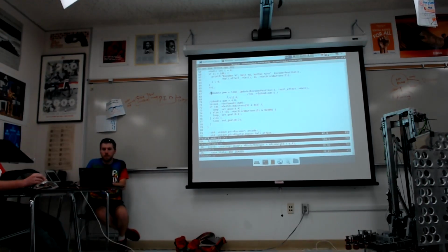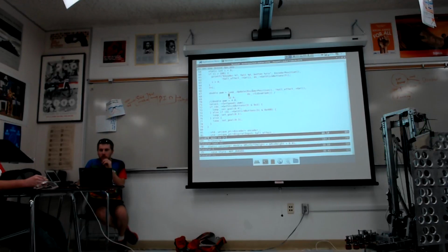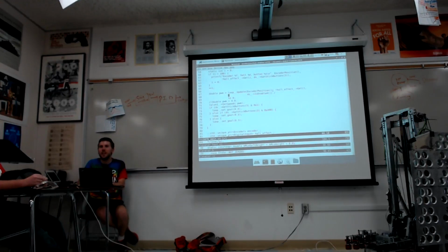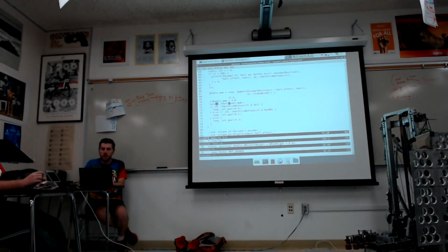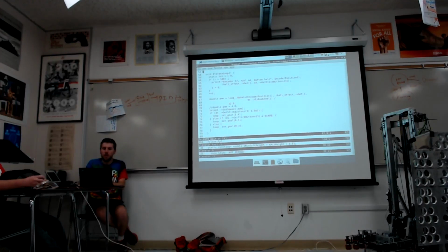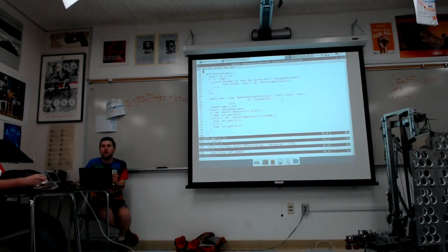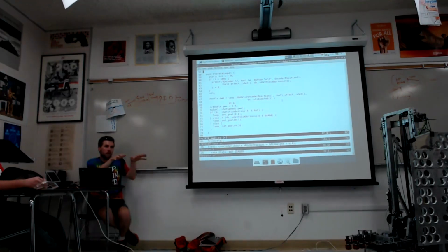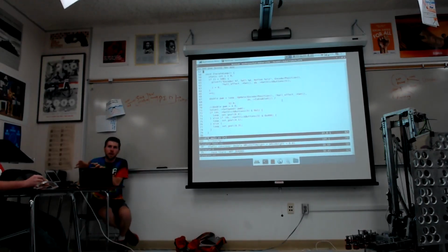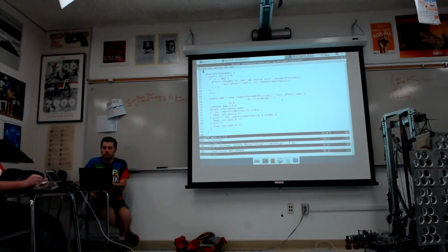We got some test code in here. So it calls loop.update, just like our simulation did, feeds it in the encoder, where I've counted the gear teeth and I think it's the right distance. And then we have our Hall effect, and then driver station is enabled. And then we convert from volts to PWM, and then we set the output. So we're able to keep most of our logic in loop.update, so we can share it between our simulation and reality. And everything in here is about translating those concepts from sensors in, and then the output of that back out to the hardware.